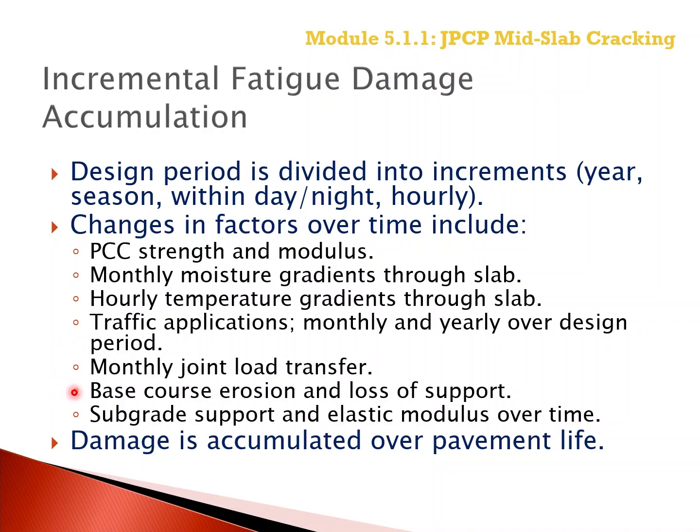The subgrade elastic modulus varies over time depending on the degree of saturation. As such, the Pavement ME software is an extensive bookkeeping process to calculate and accumulate the fatigue damage throughout the PCC slab and throughout the design period or design pavement life for a specific design strategy.